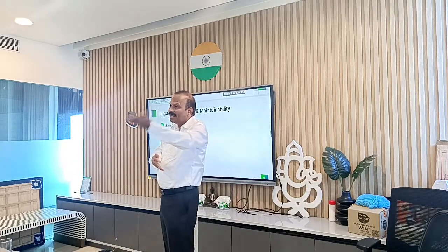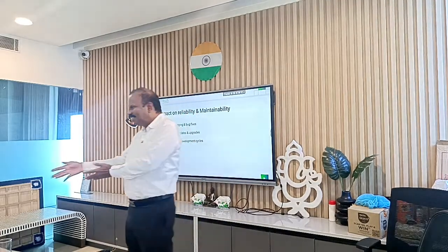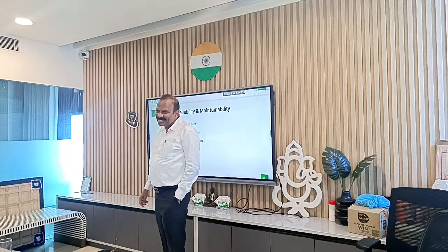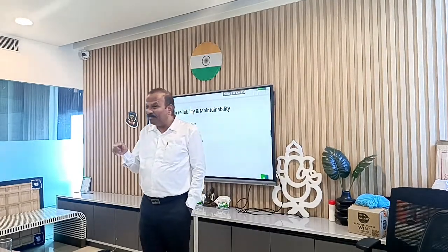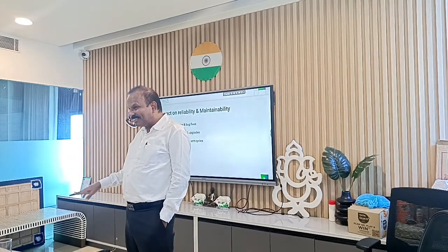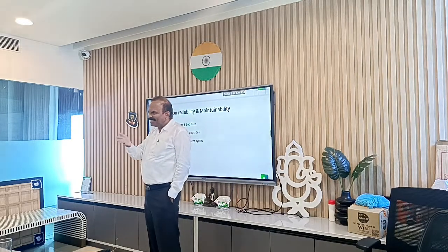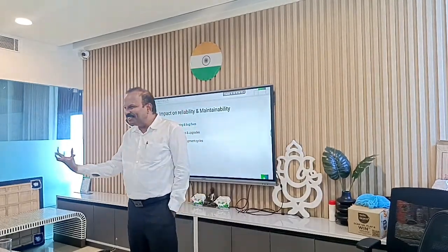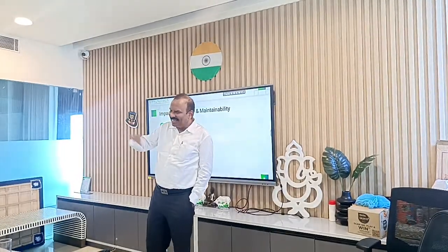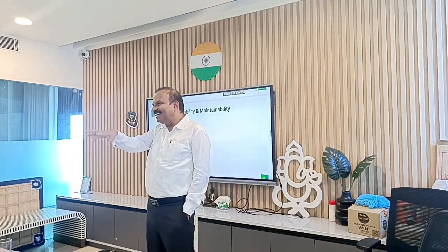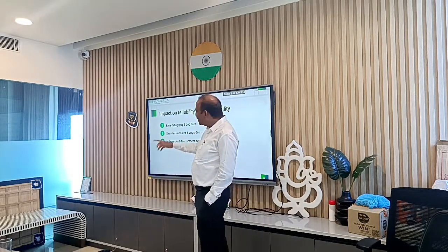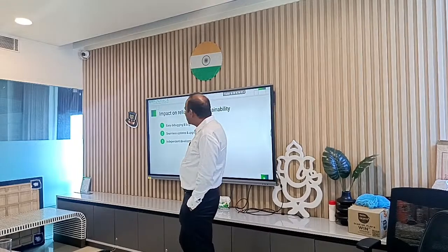Sometimes what happens is, we start using an outdated chip, and within 2-3 years that becomes obsolete. Then after 3-4 years, they say no more supply: end of life, no supply. I am using the 68K microprocessor for almost the last 25 years in the same design for the data logger. Only recently we changed. Almost 7-8 years back they said no more. Still, that particular chip is available in the market because a lot of systems were built around it. Only in the last 2 years did we start changing heavily, over the coming 3-4 years. So these are some of the issues.